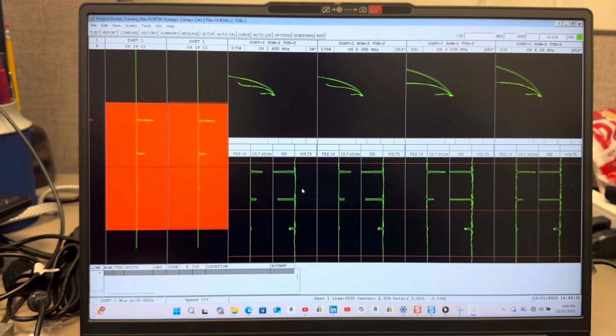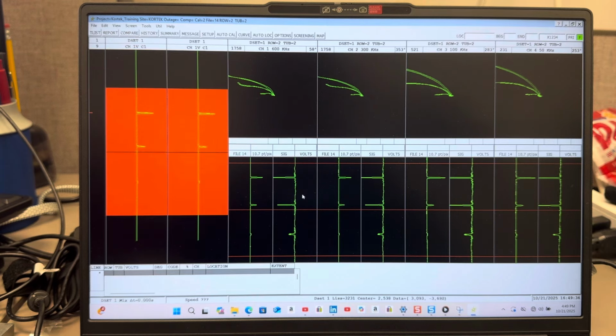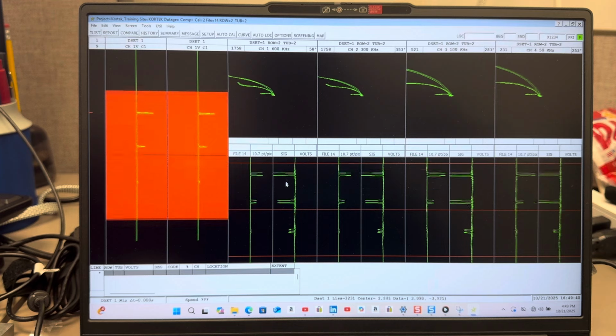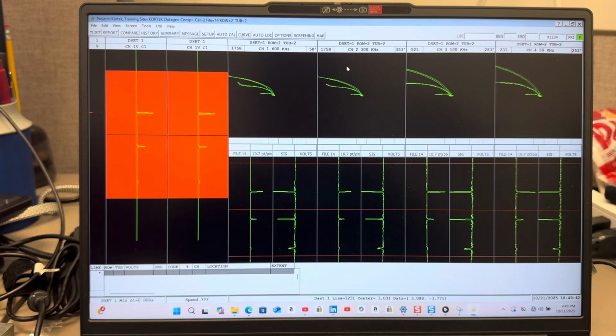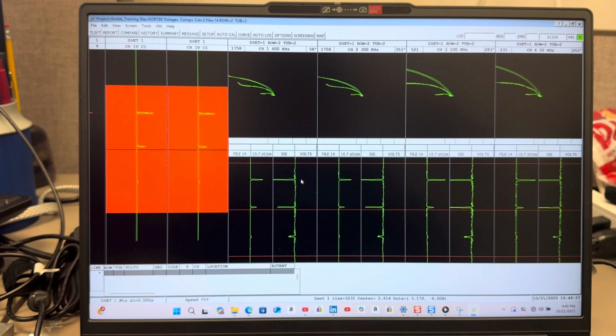Now, one thing I want to point out is surface coils, especially when they're operating in the bridge mode and you're seeing absolute signals. You're very used to seeing this type of signal with the absolute probe. But in the next video, I'm going to use a different type of probe, still with the surface, and it's going to look very similar to the differential signals that are primarily associated with tubing examples.